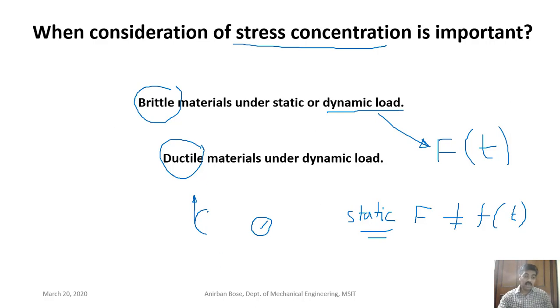You just remember that for static loading, if the material is ductile, then stress concentration can be ignored. Okay, this is a very important point. But if it is a brittle material, whether it is a static or a dynamic load, stress concentration has to be considered.